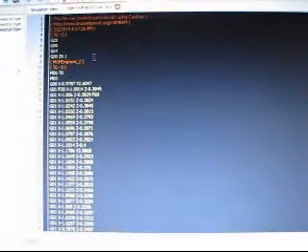But here we have our program written with CAMBAM, and we have a T0. This writes it backwards, M06 and T0. But I want a T2 over there, so I'm just going to modify that, put a T2 over there. Boom, done. And save that. The only reason why I'm doing this is for verification purposes only. I don't care about how it's going to wind up on my controller. I do manual tool change anyway, so if I had an automatic tool changer, then yeah, I would want a tool library and all that.